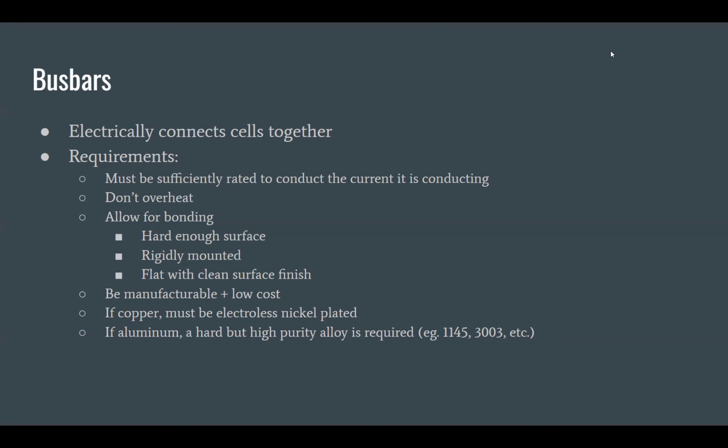And with the people who laser the bendy thing, that's the plan. Yes, we have one of our alumni, Brendan DiVincenzo, who is one of the higher-ups at a big laser company, and he can laser cut all this for us. Unlike the water jet, which has to shoot ultra high power garnet-based water at stuff to cut it and will bend thin things, a laser has really high resolution, is super fast, super easy, doesn't affect the surface finish, and it's great in every way. And zero force.